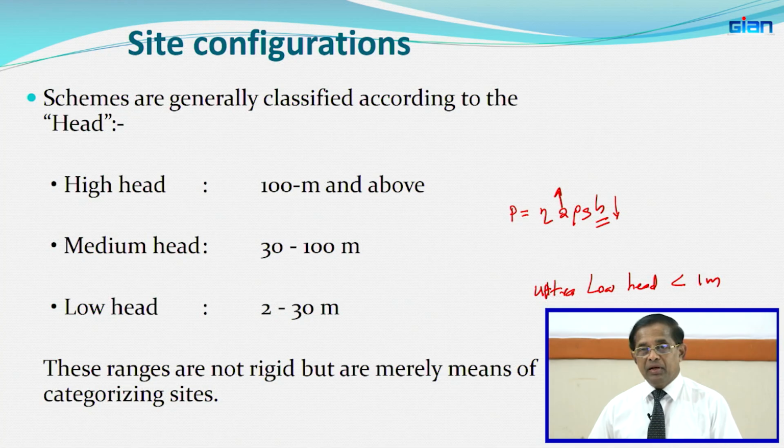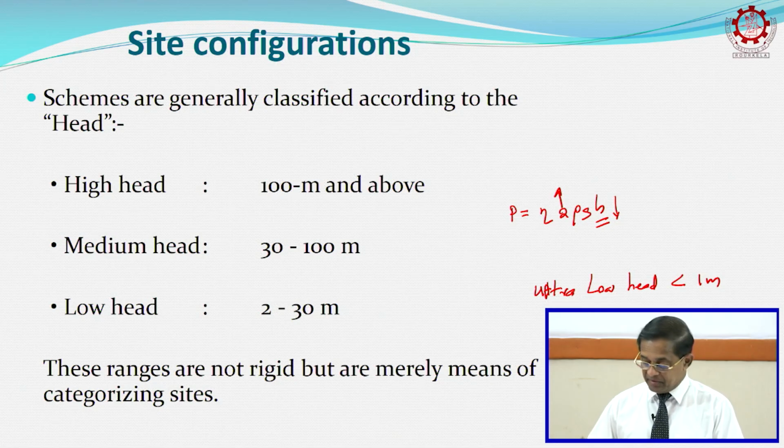I have seen similar power plants in large rivers in Germany, the Rhine river and so on. They have built dams and embedded a large series of turbine generators which are generating electricity. Because Q is high, they can be of sufficient capacity. So, note this classification based on head. You will hear these terms in the industry: high head project, medium head project, low head project.